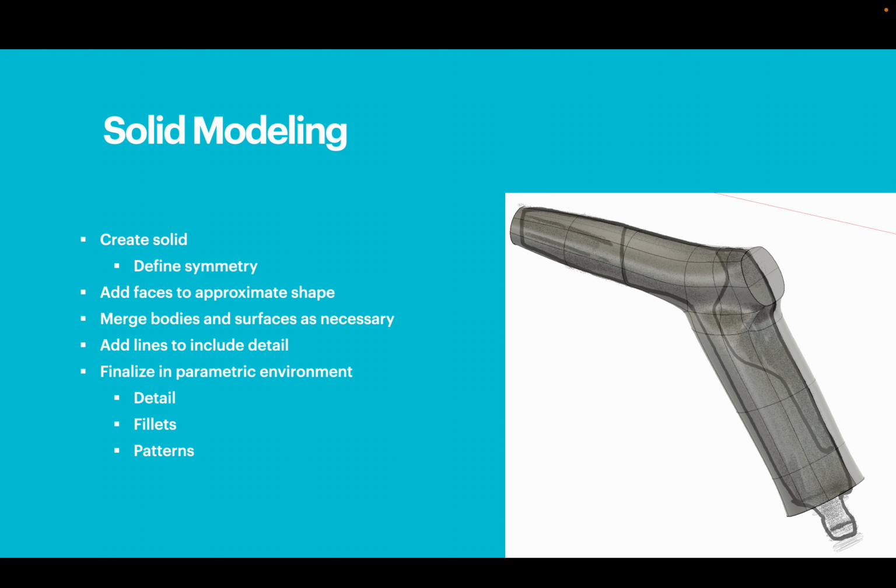Okay, so you might know from parametric modeling, like the traditional modeling in CAD, that you can either make solids, like a cube, or you can make surfaces, right? And the same thing applies for freeform as well. You can make solids and you can make surfaces. If you start out with a solid and you just delete one of the sides, let's say you make a dice and you take off one of the faces, it turns into a surface model instantly. And likewise, if you have a surface model and you close it off, it turns into a solid model. Sometimes you will get trouble trying to close off your model, and then it's a good idea to turn on box view and look at the edges and see if you can find small gaps anywhere.